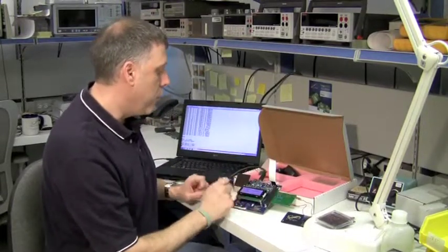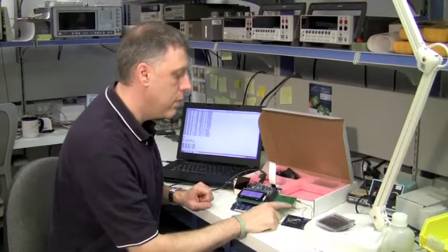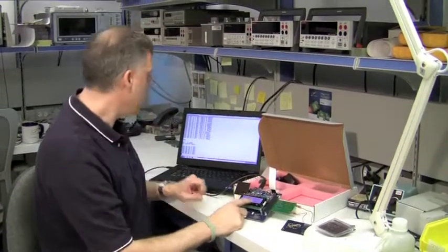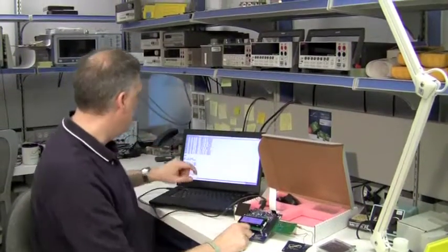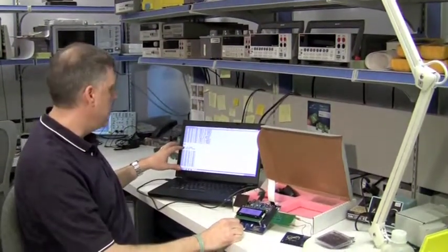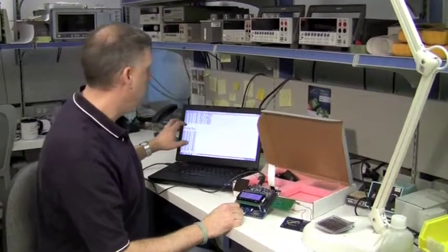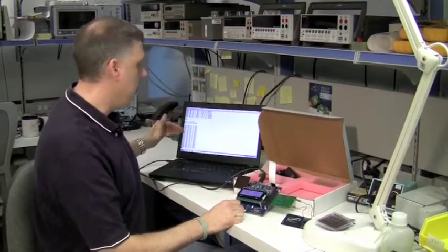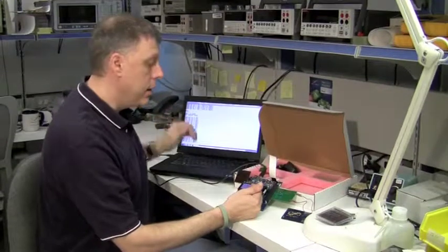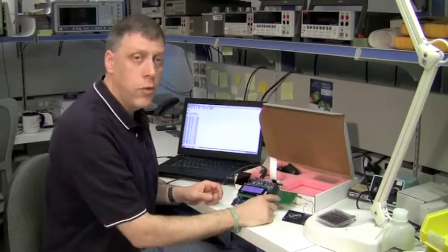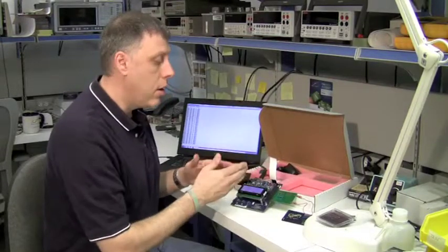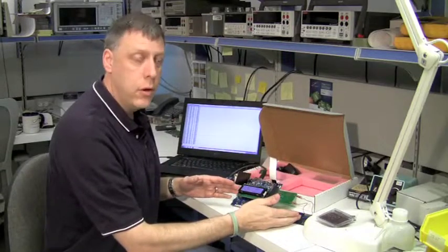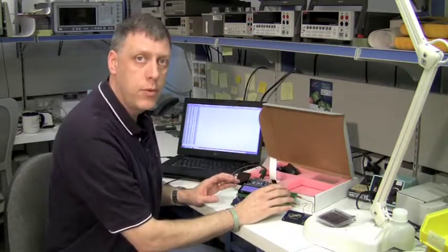So I can see I've got 4.05 volts supplied to my terminals here. I'm harvesting, on the screen here, 176 microamps, and I'm storing that information over here on my laptop. So what I can see basically is over time, and this will run indefinitely unless the MEC becomes over-discharged. If it hits a cutoff event, in other words 2.1 volts, the ADP kit will cut off the MEC from the load, protecting the MEC so it doesn't become over-discharged.